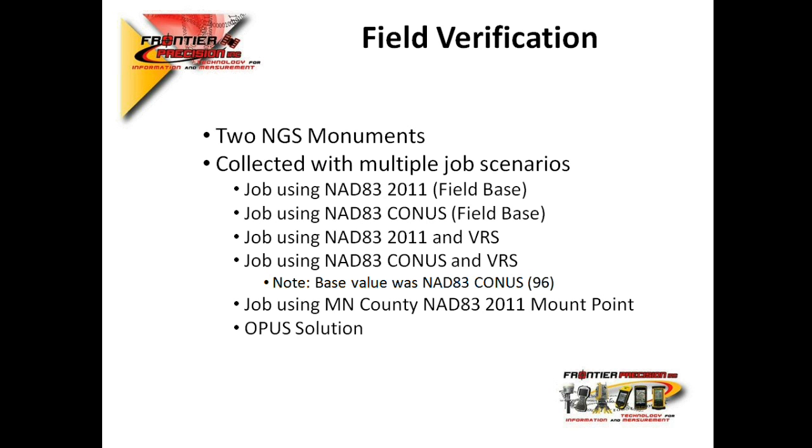Each scenario used 2011 in CONUS, the 2 different datum choices, or I should say coordinate system group choices. However, the base value was always set at the CONUS 96 adjustment because that's very typical. People will do that. So the base was set up at a 96 position, and we collected all this data.